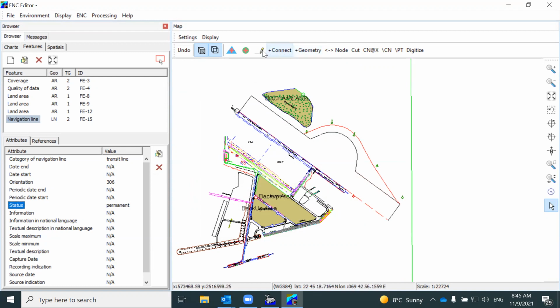Now, it's going to be a chain, but if I'm creating a line feature, sorry, line special, it's not going to be closed because a line is not closed. It has a beginning and the end. So no connection between. So it's not closed. I disable this closed option here, so it's unpressed. And now we can create this.